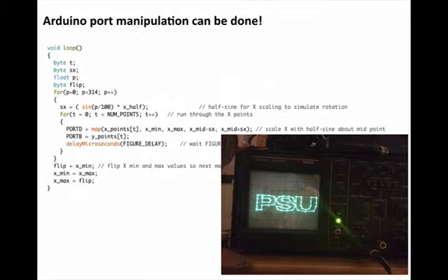On the Arduino, there are two ports. There is an 8 and a 6-bit port that you can set. You can see in this code I'm saying port D equals and port B equals. That lets me set all of the outputs on that port, the digital outputs, at once. In this case, I'm following the style of W2AEW on his YouTube channel to draw the Penn State PSU on an oscilloscope screen by making digital to analog converters through an R2R resistor network. But the idea is you can do parallel communication with your Arduino if you need to.